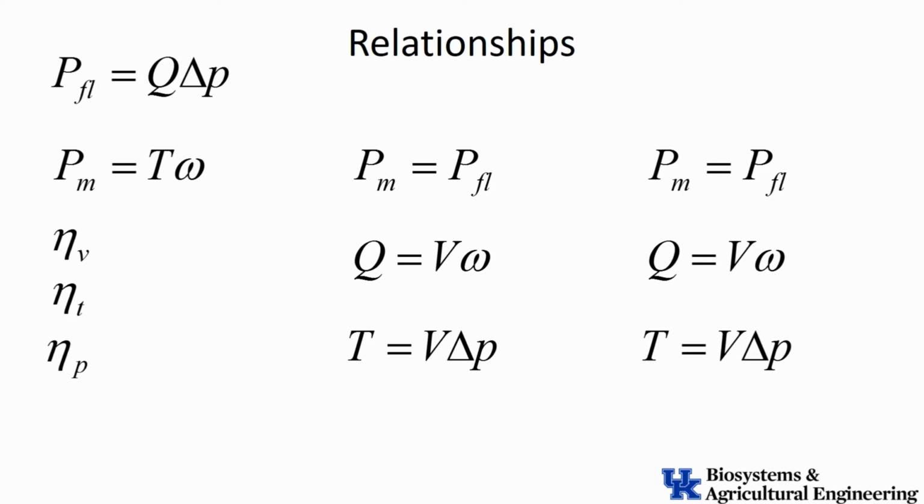We've talked about the fluid power, which is the flow times the pressure. That's a relationship of how we calculate fluid power. And then we have the mechanical power, and we've already dealt with the mechanical power with engines and the engine curves and all that kind of stuff, and that's just torque times speed. So that's how we calculate these things. And so that gives us those fundamental basic relationships of how we calculate power. Now there's some